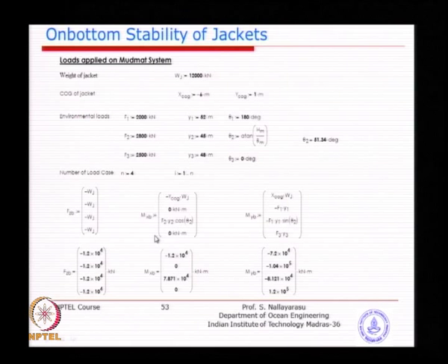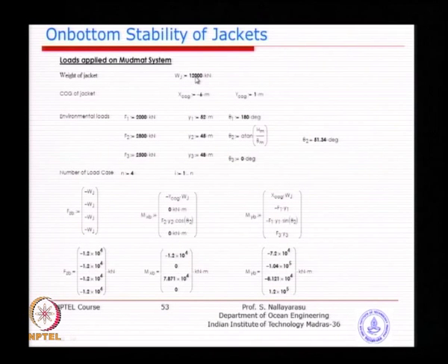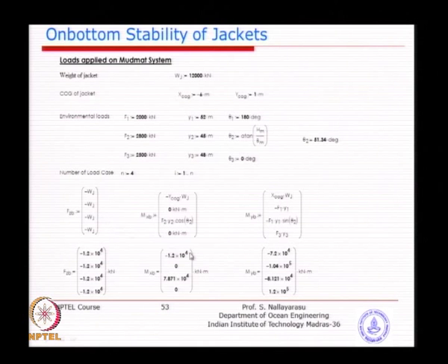And then you describe all your forces, for all, if you look at number of cases, one is the dead load case, the other one is 3 horizontal load applied in 3 different directions, just to automate, otherwise there is nothing. So, you have F1, F2, F3, and then W is your vertical load of the jacket, which is taken in the negative direction. The remaining you take the directions accordingly and resolve the components accordingly.